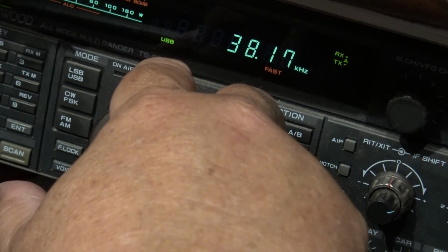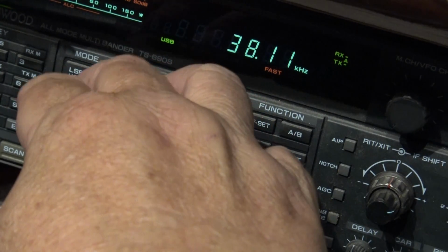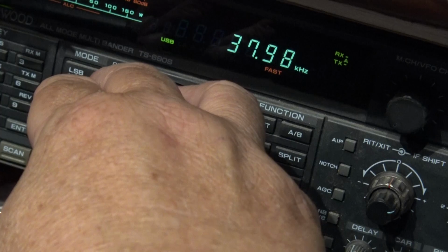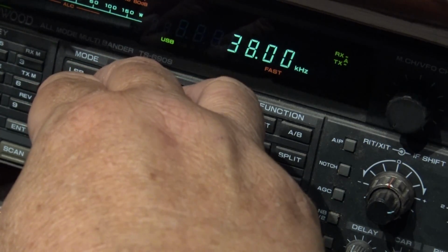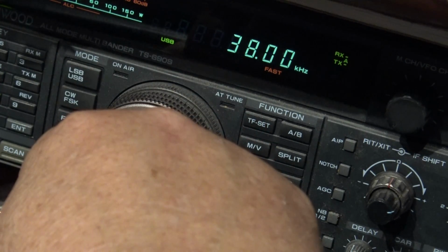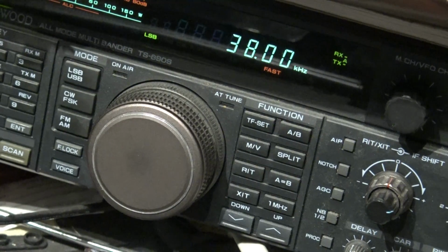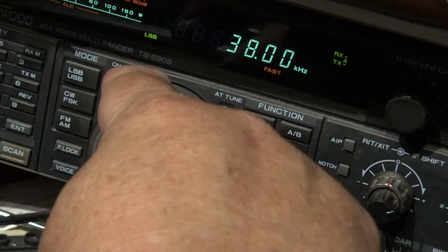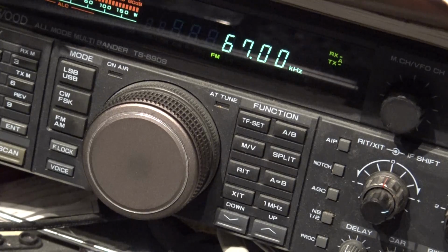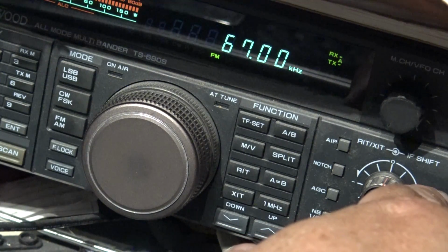That's going to be tuning in the difference signal, which is at 38 kilohertz. So that's the stereo difference signal for the actual FM station that I'm able to pick up there on 38 kilohertz in sideband mode. Neat, huh? And of course, signal strength makes a big difference, right? If your signal's not strong, it won't come in very well.